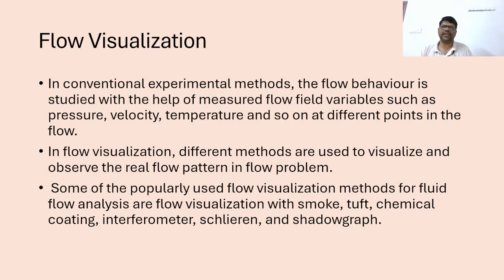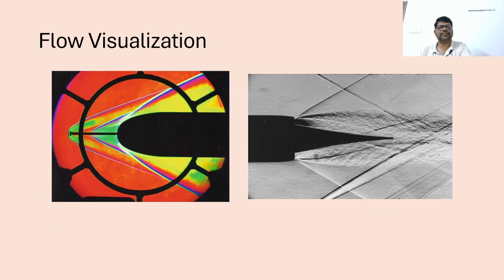But in flow visualization, we don't make any measurements. Instead, we directly capture or visualize the flow pattern over a body, right? We observe the real flow pattern in the flow problem. Some of the popularly used flow visualization methods are listed here: smoke flow visualization using tufts, chemical coating over the body, interferometry, Schlieren and shadowgraph.